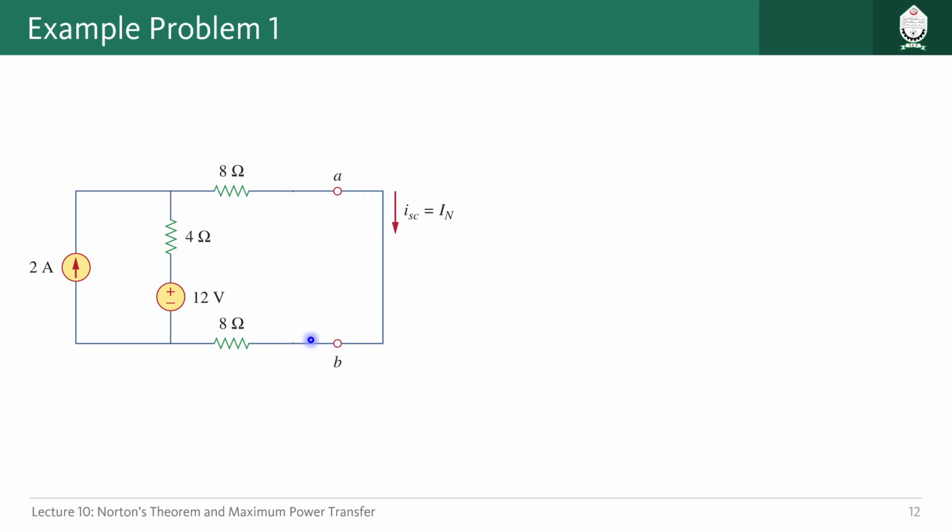Now we should try to solve this one. What we can do is use nodal analysis. For that, how many nodes do we have? Let us call this one the reference node. We will take this one as the ground, the 0 volt reference. Then after that we have this particular node here, this particular node here again, and let us not take any nodes here.